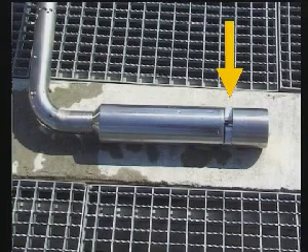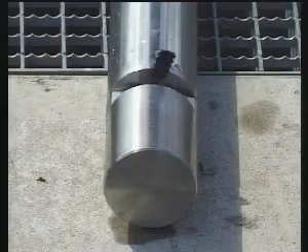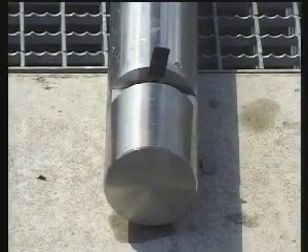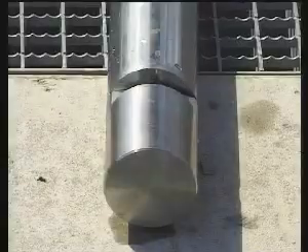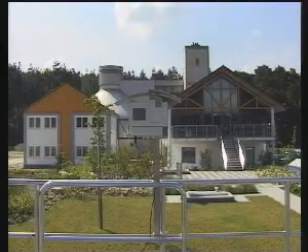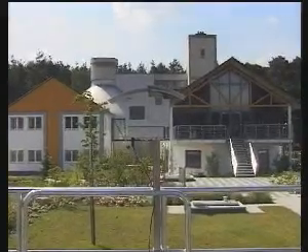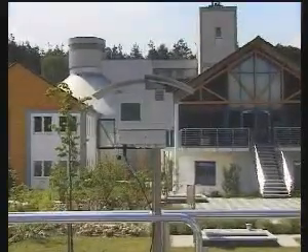The cuvette of the photometer is formed by the measurement aperture in the probe housing, which is fully immersed in the sample. The measurement aperture is cleaned at programmable time intervals by a wiper. The display unit indicates the impurity of the wastewater as absorption in units per meter, or, after appropriate calibration, as COD UV or DOC UV.